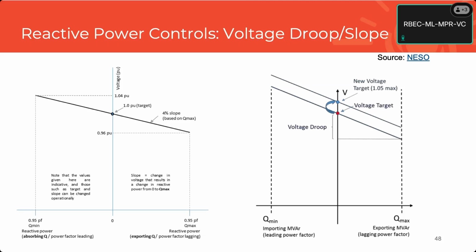And it works the same for active power and frequency. So if you have all of the generators on this sloped line, they each have one operating point for each frequency. So if they have a frequency that's slightly high, they bring their active power down by that defined amount, right? And again, you have to specifically define what you mean by that slope, but they're all on that defined point. If the line is flat and you have no droop, that's just called droop, basically.